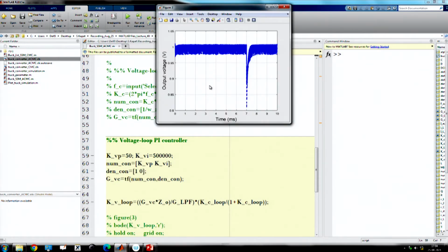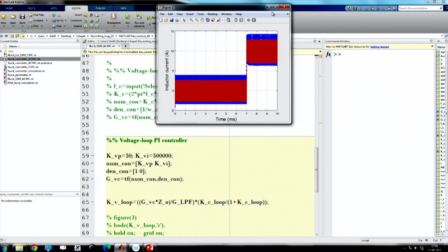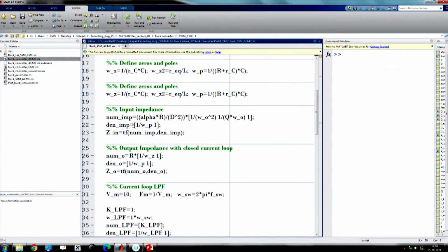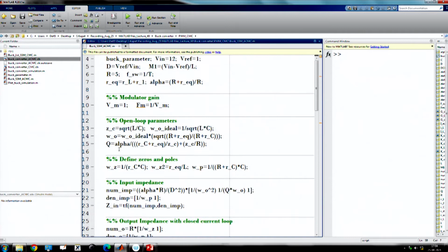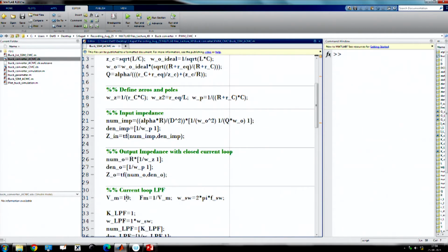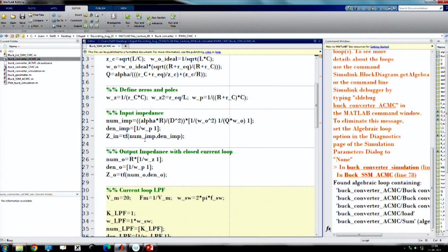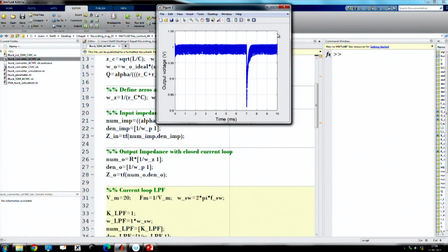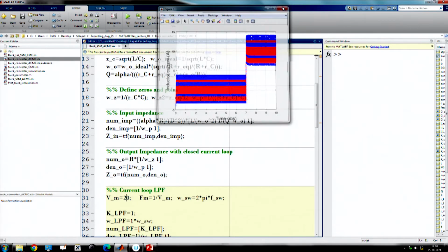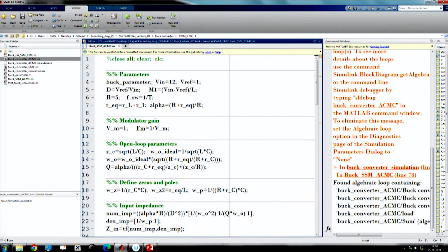So, we are slowing down, and by that way we are trying to stabilize, but at the same time we should also increase the compensating ramp effect, because the subharmonic is severe here, and by doing that we can, okay. So, we want to repeat it.